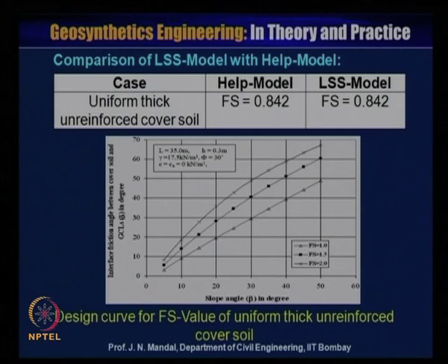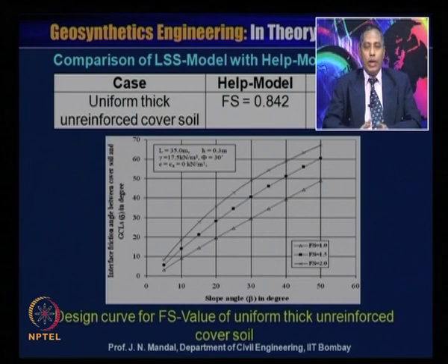So here is some comparison of the landfill slope stability model with the Helm model. Case: uniform thick unreinforced cover soil. With the Helm model the factor of safety is equal to 0.842, and the landfill slope stability model factor of safety is 0.842. So you can see that the LSS model agrees with the Helm model, that means it satisfies the criteria, that means the LSS model is okay.